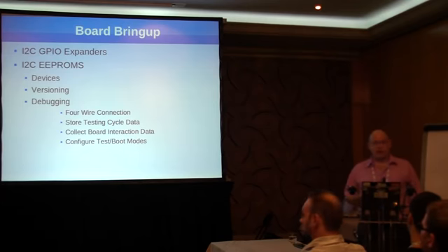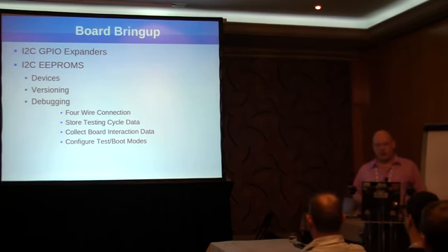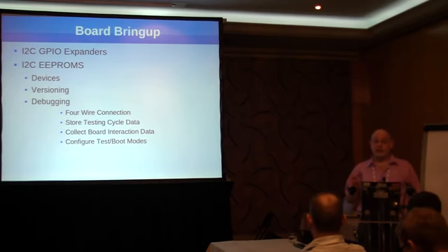And just like on the GPIO Expander where we talked about using buttons to boot into separate modes, we can actually use the serial I2C EEPROM to do the same thing. In an Android format, for instance, we can actually set the EEPROM to tell it to boot into fastboot every time, or to boot automatically in ADB. So there's a lot of different options that you can use, and it's very, very versatile.